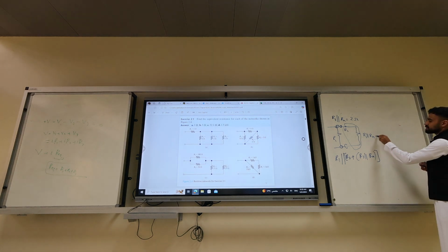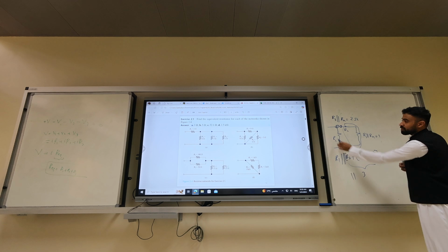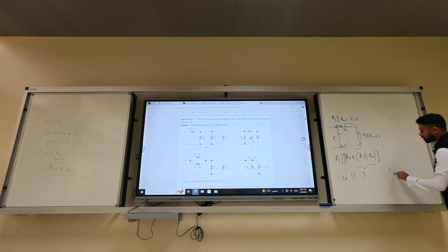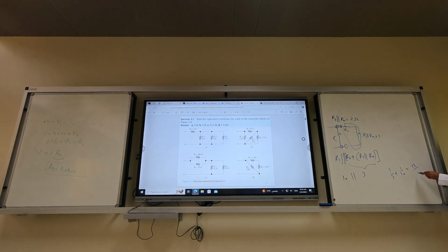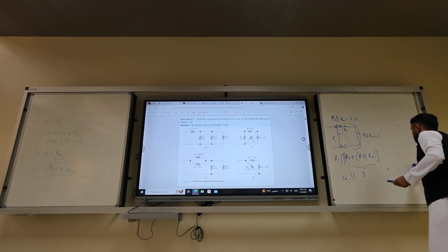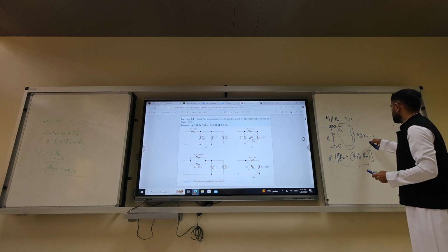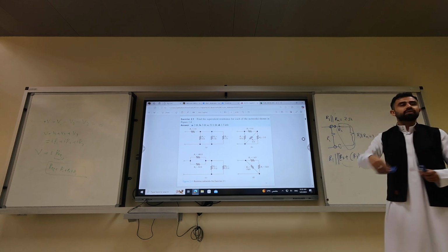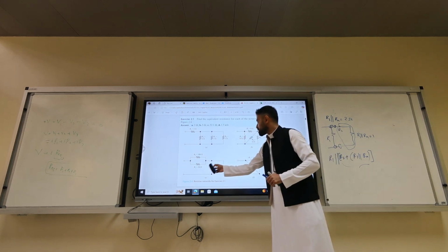So we said R3 and R4 is 1. 1 plus 2 is what? 3, right? Yes. 3 parallel with R1, 10. What's 3 parallel with 10? Sorry, no. It's 2 and 10, not 3. Plus 8, so it's 10. Parallel with 10, the R equivalent will be 5. So what is R2? Oh, 8. 8 plus 2 gives 10. 10 parallel with 10 is 5. Yes, right. So what's the final answer? 5.